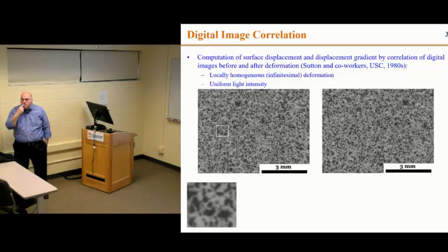3 millimeter or micrometer? This is 3 millimeters, but this particular method, unlike other optical methods that are based on light, for example, interferometry methods, right? This does not have an inherent length scale. If you're using a technique that's based on light, the length scale is limited by the wavelength of the light you're using. Maybe a half or a quarter would be about the smallest you can get, right? This is a scaleless method.